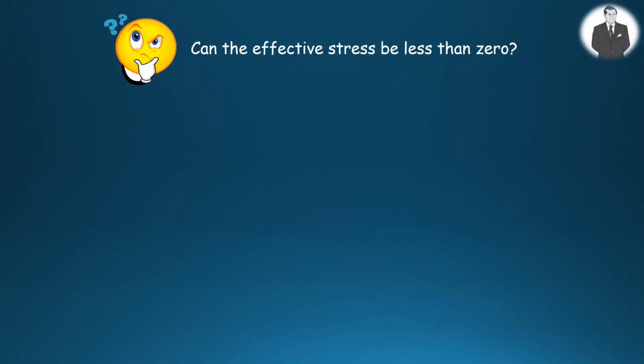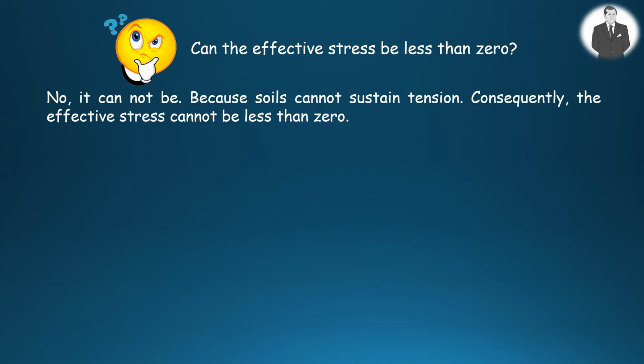Can the effective stress be negative? In other words, be less than 0? No, it cannot be, because soils cannot maintain tension. As a result, the effective stress cannot be less than 0.